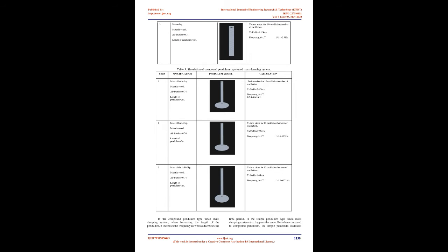The required tools are: brush tool, B, used to draw shapes with brush strokes. Circle tool, C, used to create circles. Drag tool, D, used to move objects while the simulation is running. Tracer tool, E, used to attach a tracer to an object, which draws the path of where that object has traveled. Fixate tool, F, used to weld an object to the object behind it or the background. Knife tool, T, used to cut polygons along a drawn line. Box tool, X, used to create rectangles, or squares with shift.